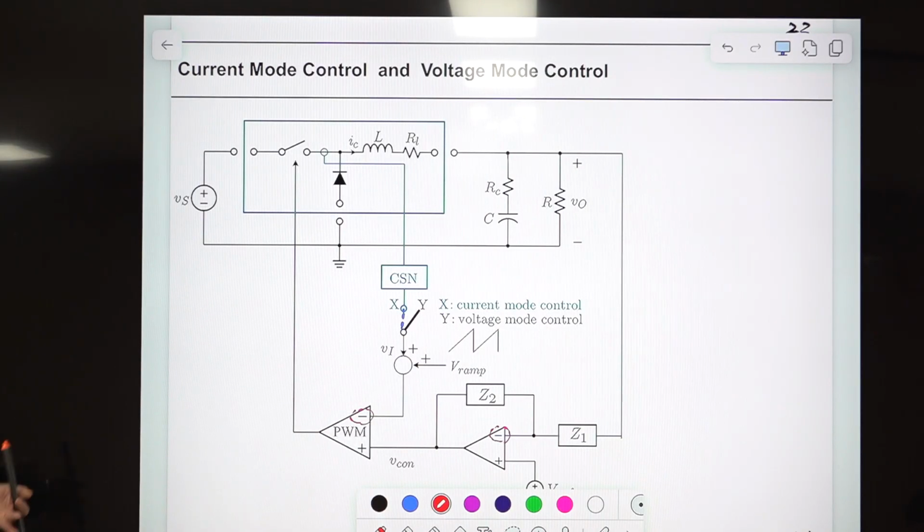So when you are writing a paper about the comparison between voltage mode control and current mode control for 3 different converters, you can use only this one diagram. Then that can represent 6 different configurations: 3 from the power stage, 2 from the control scheme. So this is a very convenient way of representing PWM converters.